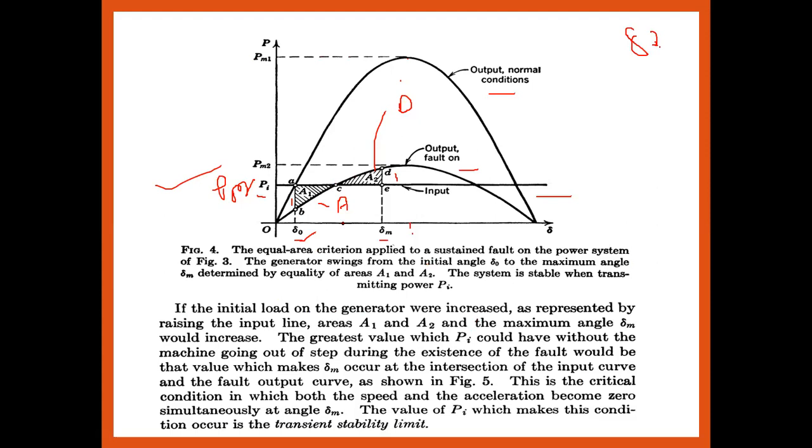Now, when the load increases, what will automatically happen to the load angle? In the second condition, deceleration, it will increase again. It first decreased, now it increases again. Now it should move from C to D, and D and E are studied by what? They should be studied by the decelerating power.